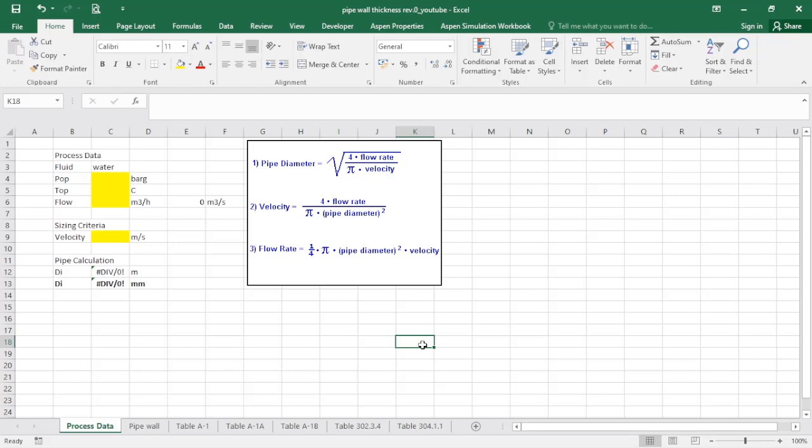One of the activities of a chemical process engineer working with plant design is to deal with pipe sizing for transportation of fluids. And to be able to do that, we need to have the initial heat and material balance of the system, or at least the requirements of the fluid that must be transported. So based on that, I will share with you here an example where we have water, and based on the process conditions, we'll do the preliminary pipe sizing of the system.